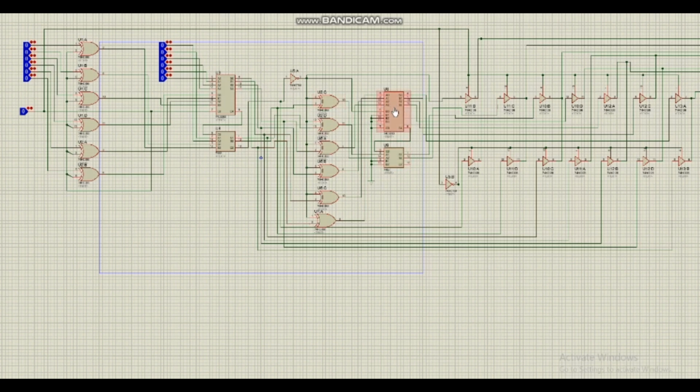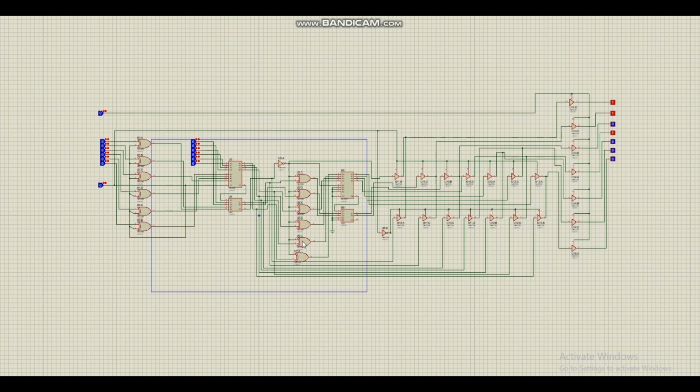So we have a 6-bit parallel adder. The first 6 bits are coming from the previous results, and we need to add 1 when we do not have an end carry. So this inverter will feed through this B0, which means we are adding a 1 only when we do not have an end carry, and we are also reversing it, so we can get the perfect result even when A is less than B.